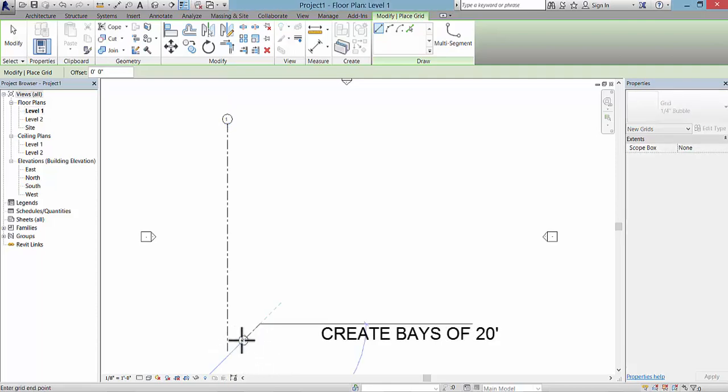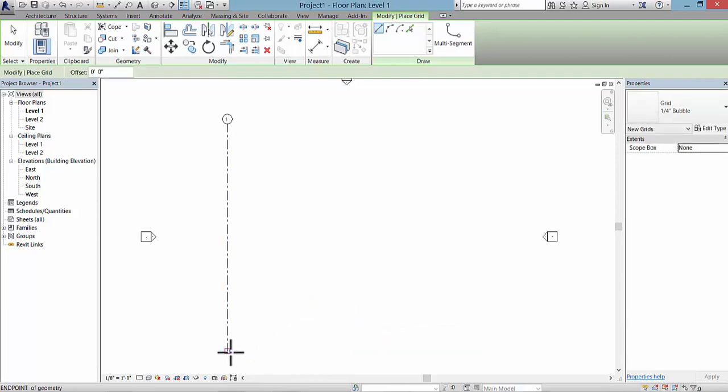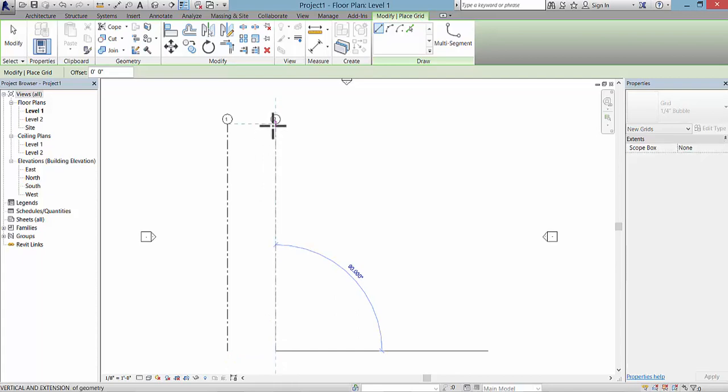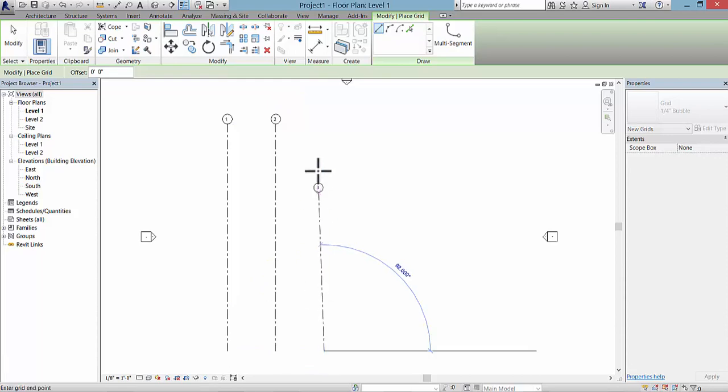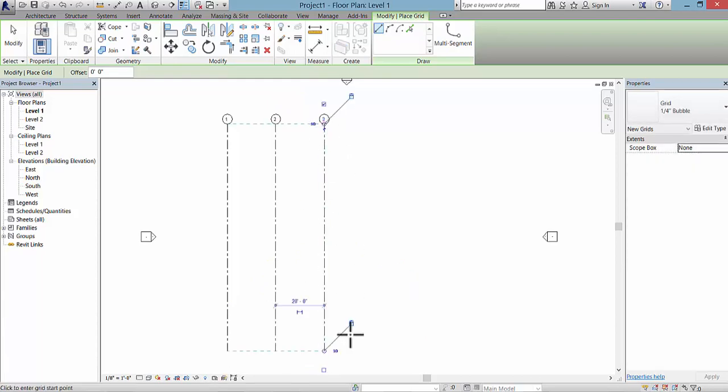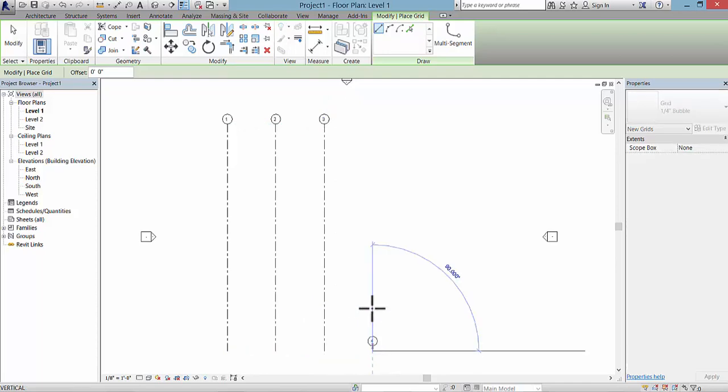We'll just go ahead and create here a base of 20 feet. So if you rest your pointer at the bottom of this grid and come across here to 20 and click, you can pull your mouse up until it gets to the top and click, and you've got a second one. You can see already that once you've placed these, you will be able to change them. I'm going to go ahead and put here 4 column bubbles. We're just going to keep this simple.